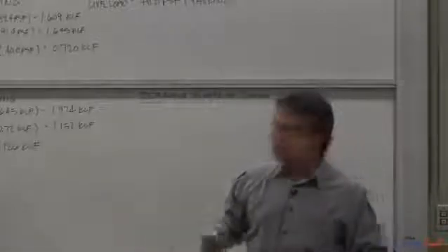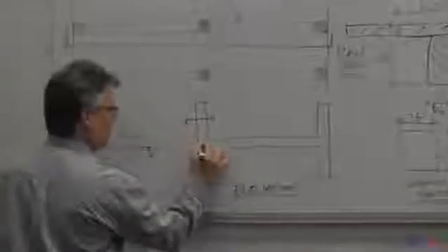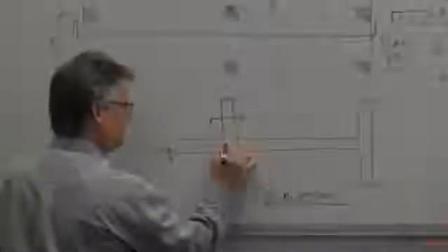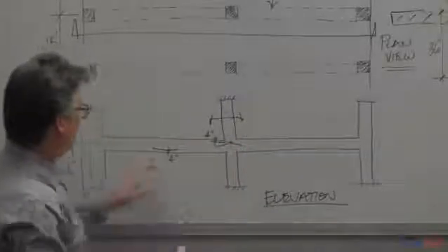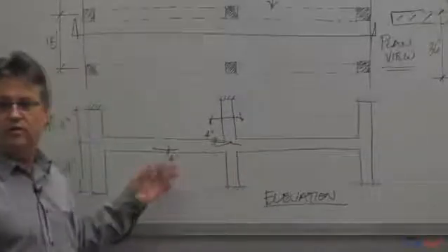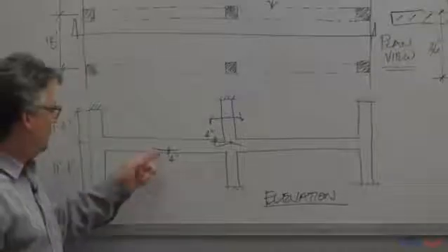Okay, I want you, just as we've gone along, to use a 4-inch maximum CGS. It can be less. At the top, it's not going to be less. Pretty much just what we've done all along. I've told you 4 inches is a very reasonable and comfortable CGS to the face of concrete. So we're going to assume that.